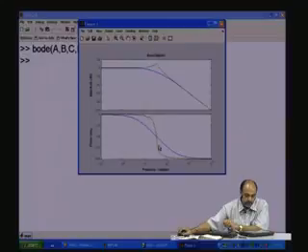It falls much more sharply in phase by 180 degrees. So, it is not a gradual change to 180 degrees. Magnitude filtering wise they are more or less the same, because they are going to have the same minus 40 dB per decade, but phase wise it is going to jump quite fast to 180 degrees.